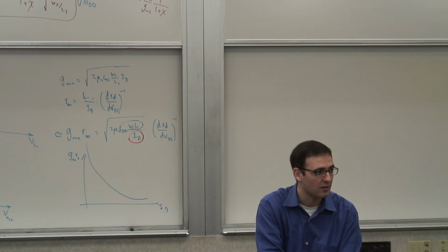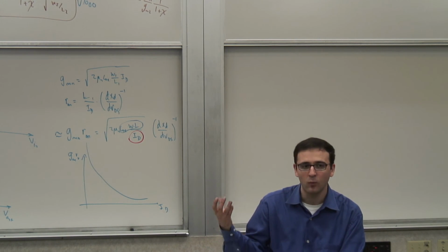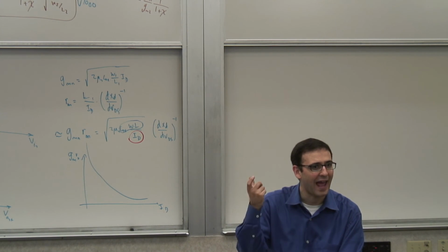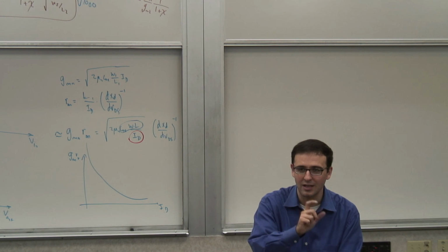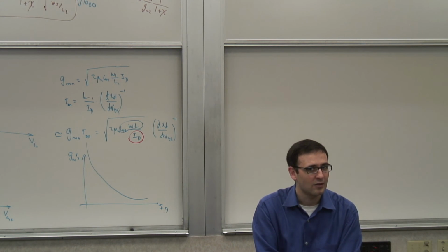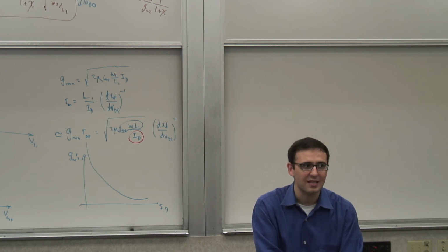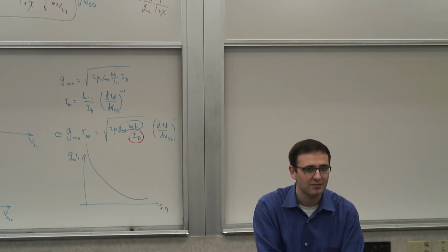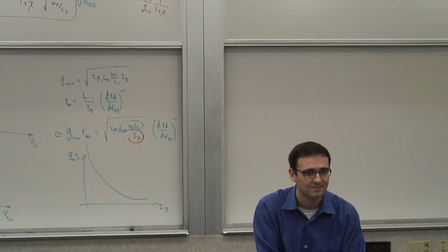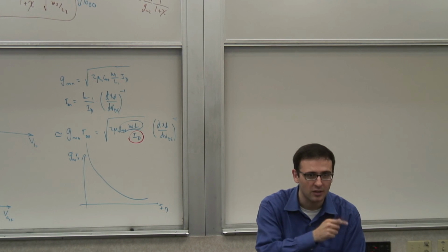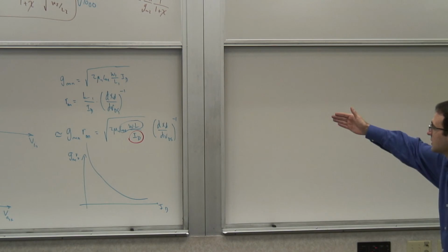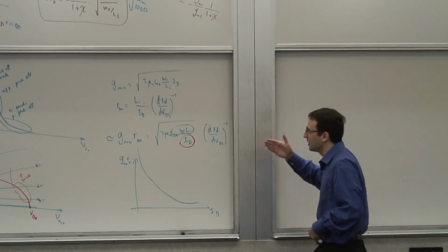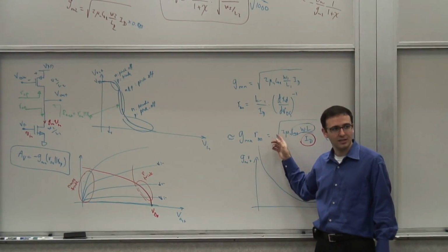lower and lower VGS. So based on this model, what is the VGS at ID equals 0? VT, right? Which means that you're at the edge of turning on. But in reality, if my VGS is exactly VT, is my drain current exactly 0? That would be subthreshold current, right? So at some point, the fact that I've ignored the subthreshold current in conduction has resulted in an inaccuracy